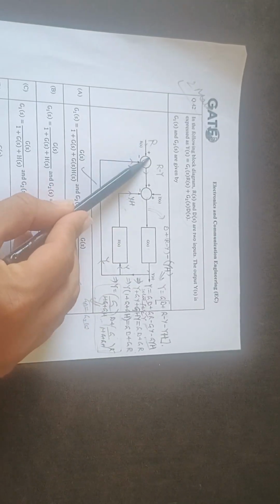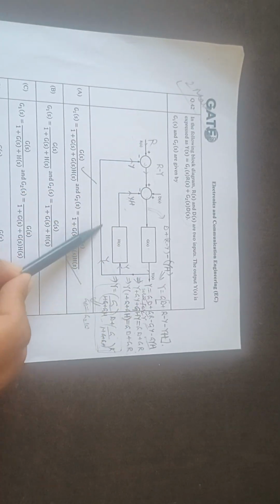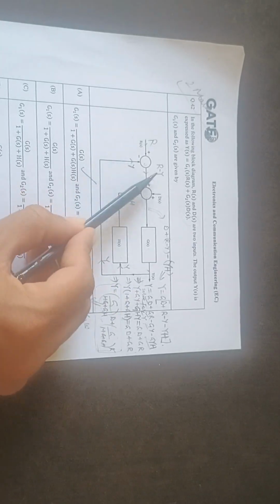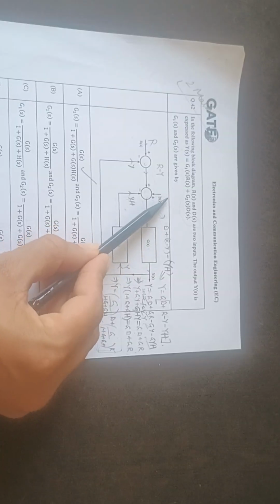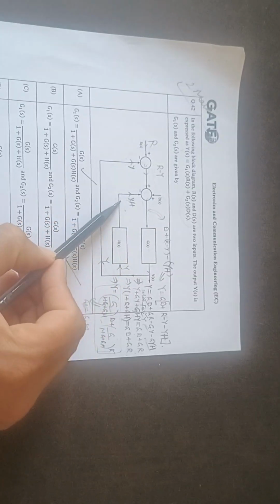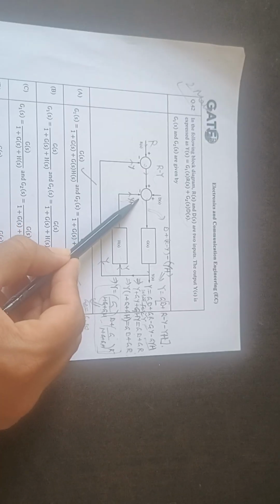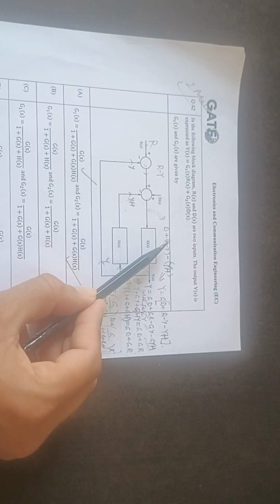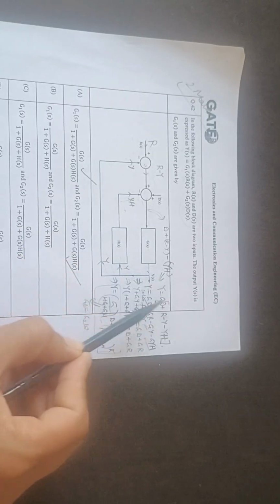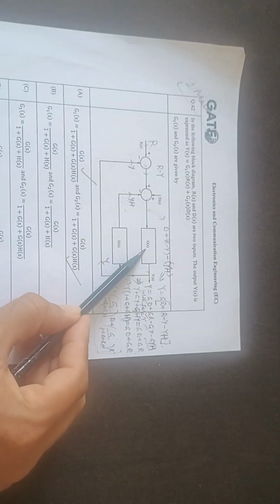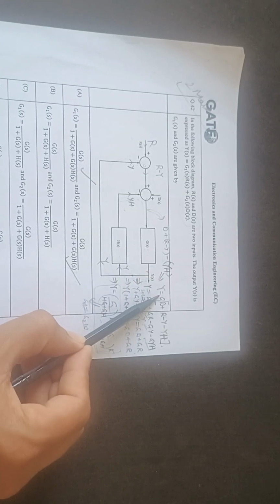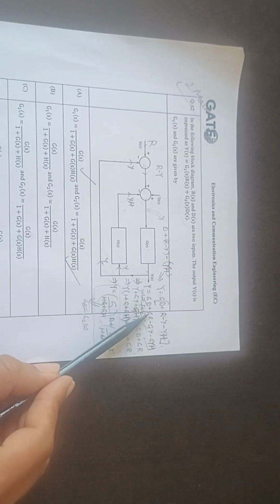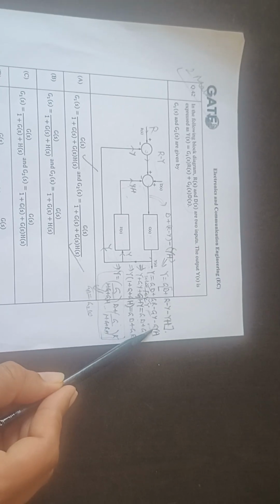So here R is coming, here Y is coming, so here Y will come, here Y H will come. So this will be R minus Y, and this D is coming, R minus Y is coming, and Y minus H is coming. So we will add these two and subtract these two, so here it will be D plus R minus Y minus YH, and therefore output will be this multiplied by this G(s), so G multiplied by D plus R minus Y minus YH. So Y is equal to GD plus GR minus GY minus GYH.